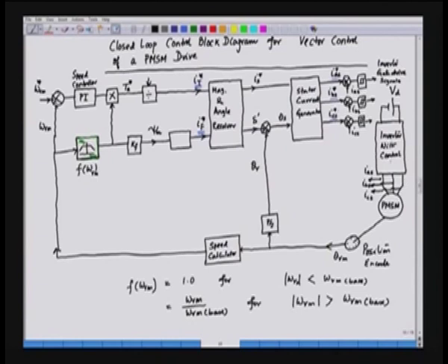And then we can have an inverter with current control. We compare the reference currents, these stars are actually the reference currents, IAS star, IBS star and ICS star, which are the three reference currents of the respective phases. They are compared with the actual currents, and the actual currents are obtained by Hall sensors. So, these are the actual currents IAS, IBS and ICS. They are obtained by having Hall sensors in the three phases of the stator of the PMSM drive.